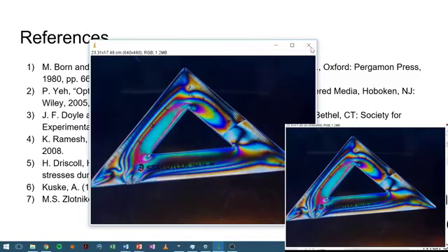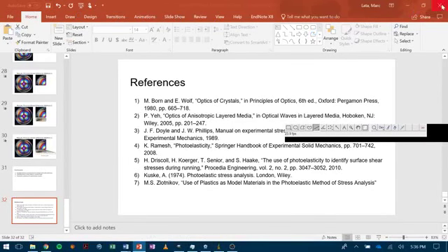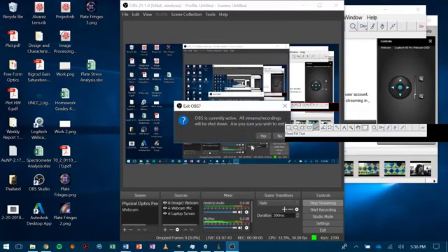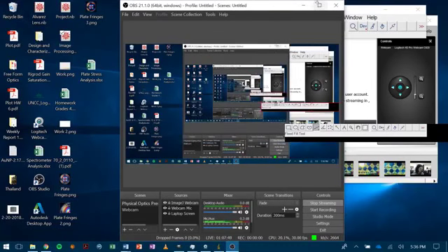Heat treatment is a very essential step in any production, for any material, because during machining you apply a lot of stresses to cut and shape it. After that your material may be very fragile, and when you start to use it, it will break quickly. So heat treatment means to release the stresses, make the material more elastic and stronger again. For every type of material, there are very precise steps.